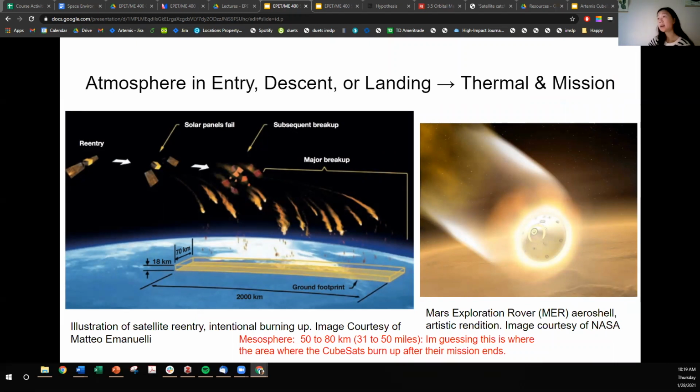Okay, as we were talking about re-entering the atmosphere, objects entering an atmosphere experience atmospheric drag, which puts mechanical stress on an object, and aerodynamic heating, caused mostly by the compression of air in front of an object, but also by drag. These forces can cause loss of mass, which is called ablation, or even complete disintegration of smaller objects. An object with lower compressive strength can explode. For Earth, atmospheric entry occurs by convention at the Kármán line at an altitude of 100 kilometers above the surface, while, for example, at Venus, atmospheric entry occurs at 250 kilometers.